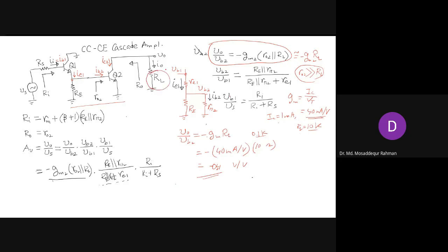So on the output side, you see that the gain is heavily dependent on the value of this load resistance RL. Usually we assume a high value for the load resistance, but that is not always the case. In many situations you cannot control the load resistance. The load is something external, whatever you connect to it, like when using a microphone. You cannot control the resistance of the microphone. Whatever comes from the manufacturer, whatever is inside, that is the load resistance, so you cannot change it.